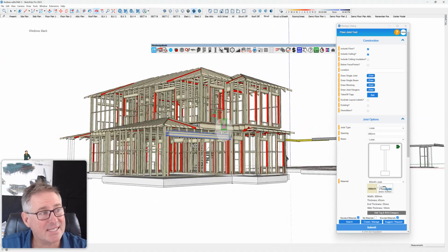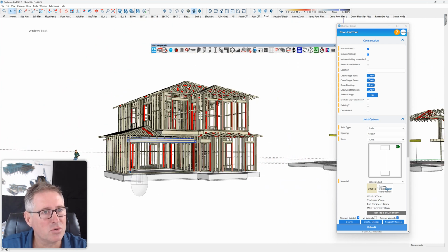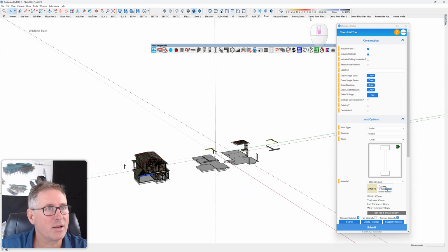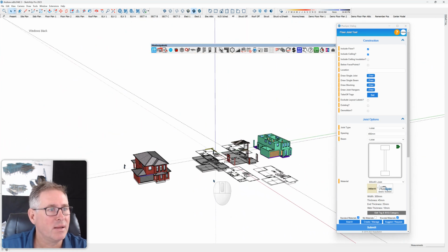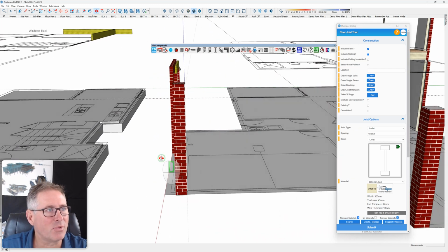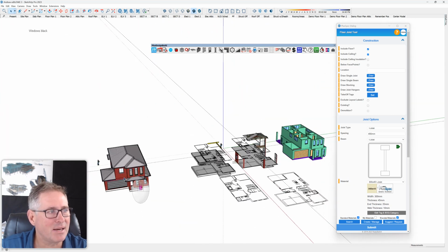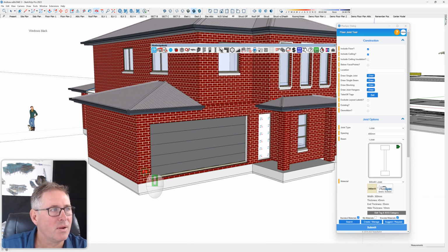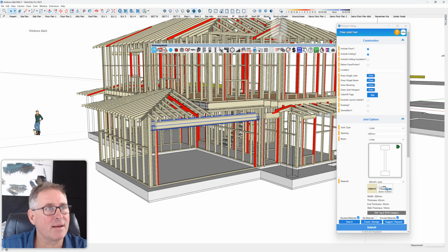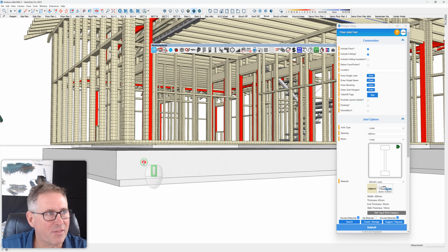The next thing is that Matt didn't actually pay attention to how I had gone about drawing these walls. You can see that they're a different type of wall, and they should have been set down to suit the slab step down, because when I go to structure, it shows me quite clearly that nothing's holding that wall up.